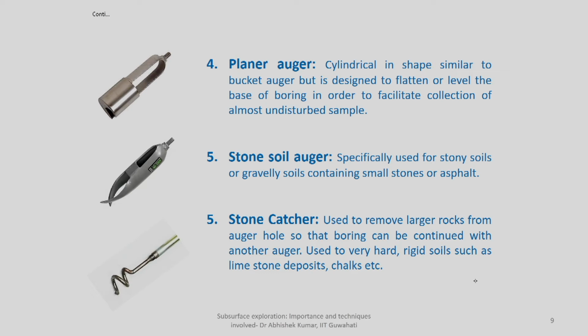So that's how you can go ahead in coordination with sampling and boring simultaneously. You remove it, then do the sampling. Once your sampling is done, you have to go for a deeper depth. You lower this kind of auger. It keeps on scratching the material, collecting the material, then it will bring it onto the surface. You lower the sampler and repeat the same exercise.